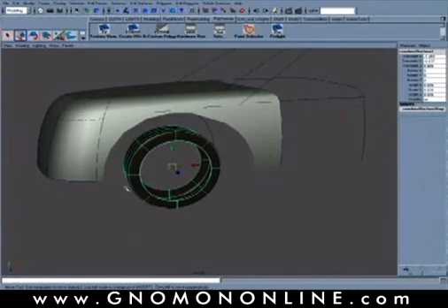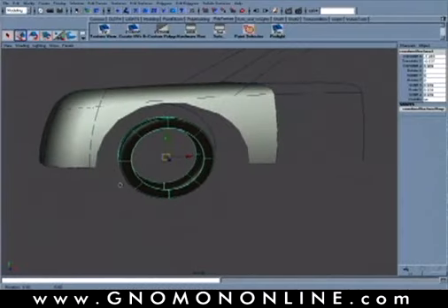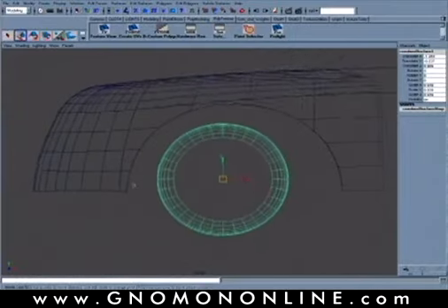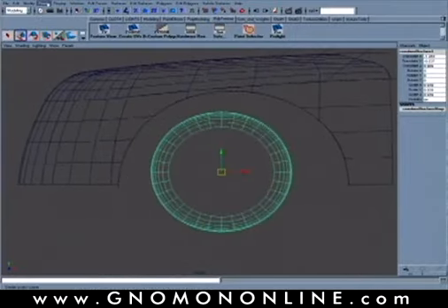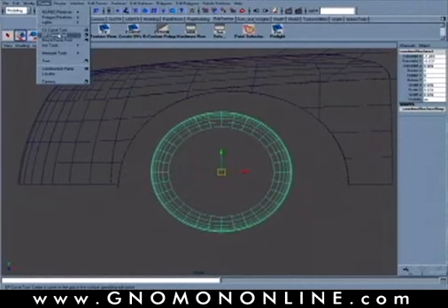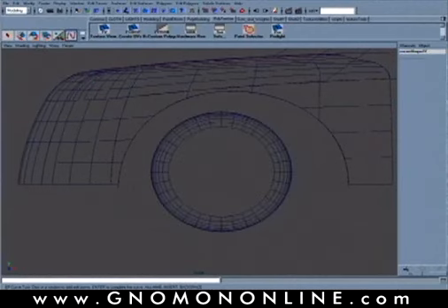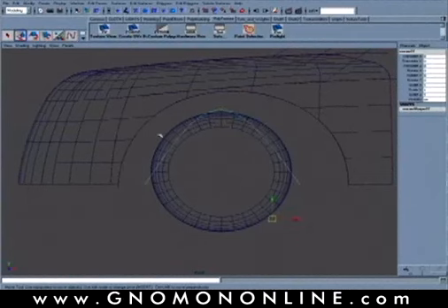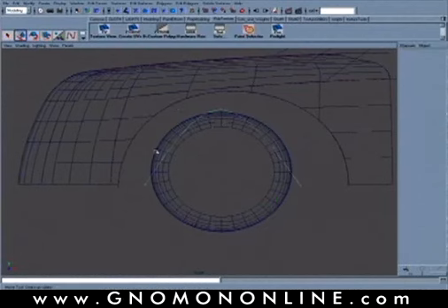And then the next thing I want to do is actually create my wheel opening. Okay, and this will be the actual wheel arch that goes around the tire. So in this case I'm going to do this from, again, a side view. We're going to start out drawing with my edit point curves. Basically give me 3 separate points with the edit point curve to create that more pointed section here. And then we'll go in with our CVs or our curve editing tool and start to manually kind of position how we want that arch to fit over the surface.